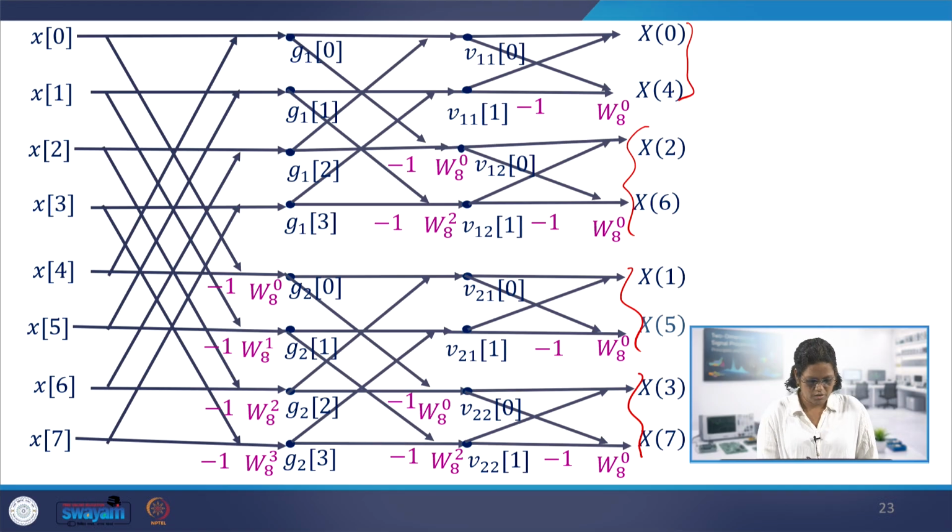Here you can see the complex multiplications and 4 butterflies in each stage, as we did in the DIT algorithm. The computational complexity remains the same. So DIF has the bit reversed outputs. With 1D FFT, Fast Fourier Transform, we did the DIT algorithm and the DIF algorithm. So these two FFTs are useful.